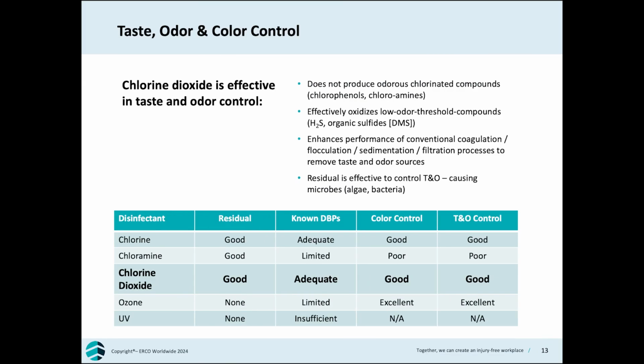Besides iron and manganese oxidation and removal, chlorine dioxide treatment can also control many other taste and odor causing agents. As Scott mentioned, when chlorine dioxide was first used in the United States in the 1940s at the Niagara water treatment plant, chlorine dioxide was used to control phenol-related taste and odor of the water.